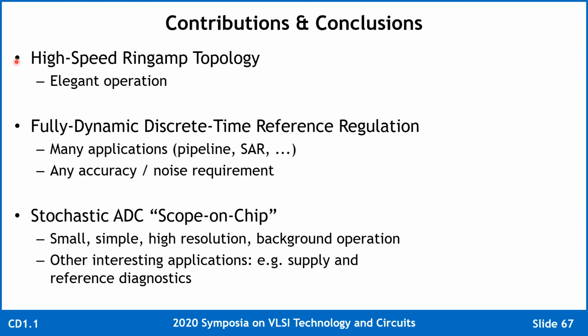In this talk, I have presented three main ideas. The first is a high-speed Ringamp topology with a particularly elegant mode of operation. The second is a fully dynamic discrete time reference regulation system that can be applied in many cases and can achieve any accuracy or noise requirement for discrete time regulation. The third is a stochastic ADC scope-on-chip-based transient waveform reconstruction system, which is small, simple, high resolution, and capable of background operation. And it leads to other interesting possibilities and applications, for example, supply and reference